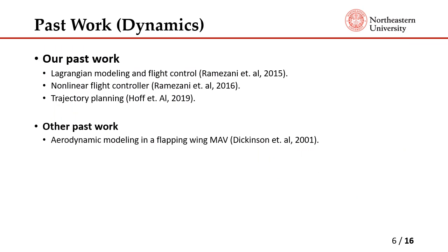Other past works we have done are on the dynamic side of the simulation. We have the Lagrangian modeling, nonlinear flight control, and trajectory planning done by Ramezani and Hoff. Other past work includes the dynamic modeling of the flapping wing done by Dickinson, where they characterize the lift and drag coefficients on a small scale insect robot. We're going to use the same lift and drag coefficient model they have in this simulation of the aerodynamic forces.